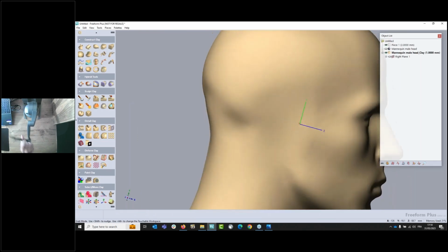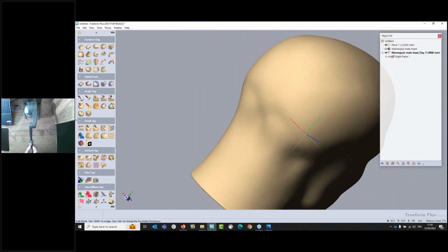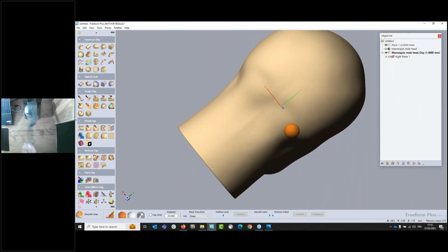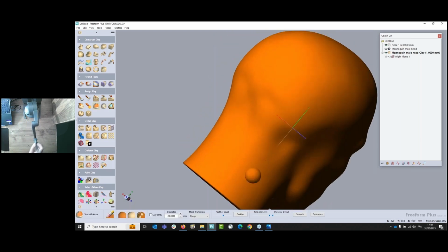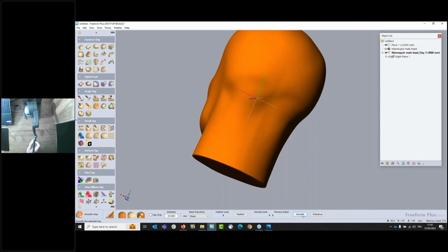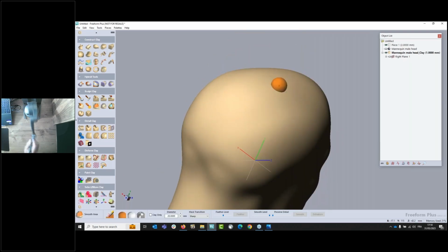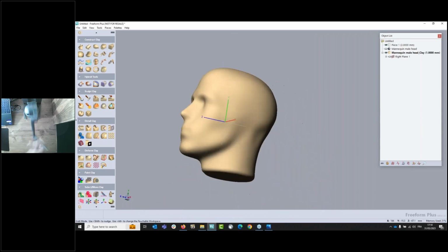Next step will be to make a smooth on it, because as you can see, there's the parting line of my mannequin head here. So I will stay in the same tool, select all my objects, choose a very big smooth level, then apply a global smoothing on the object, one more, maybe a third one. Like this, I'm sure the surface will be perfectly nice.